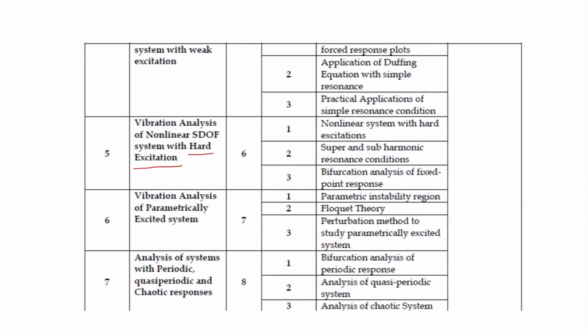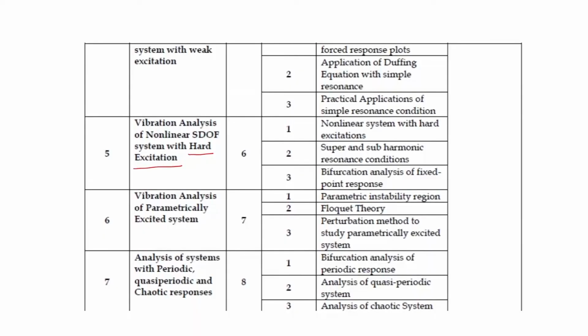In the quasi periodic response, there is a relation between the frequencies. In a quasi periodic system the frequency ratios are incommensurable, that means the ratios are irrational numbers, like root 2, root 3, root 5. Then we can have this quasi periodic type of response. For example, you may know the beating phenomenon. The beating phenomenon can be represented by a quasi periodic response.